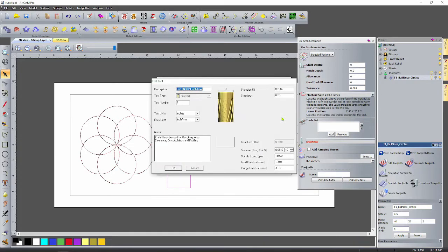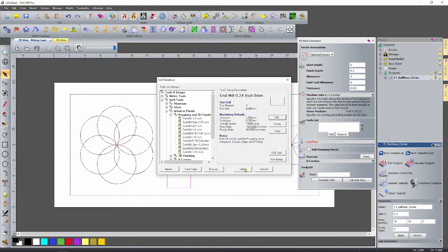Edit. This is going to be tool number 2, and because it's metric, 6mm diameter, and a step down, we already talked about that, so everything looks good. We don't change these things either. Just check the tool number 2, that's okay, and select.